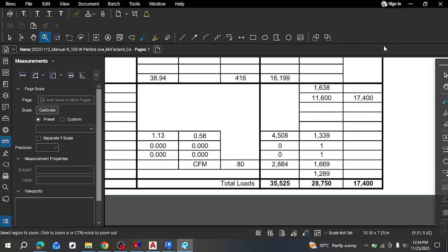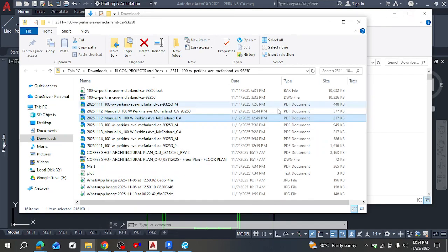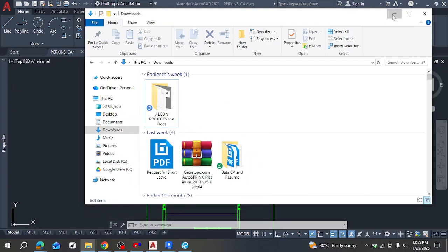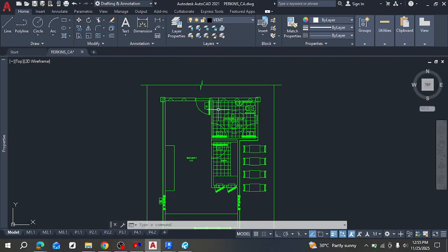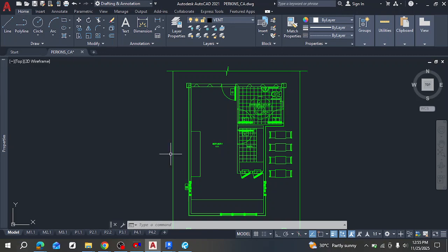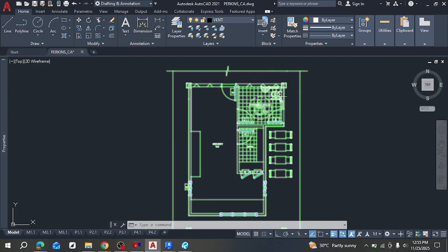You're rounding it up. Now, when we calculated for this space, it gave us 400 CFM. And 400 CFM is just 1 ton. By the time you add the small space here, 450 is still roughly 1 ton, but 36,000 is 3 tons. So in a case like this where your rule of thumb is giving you a different value